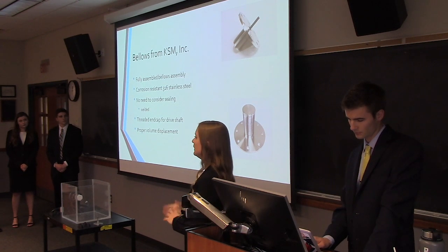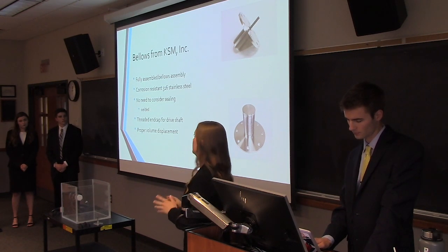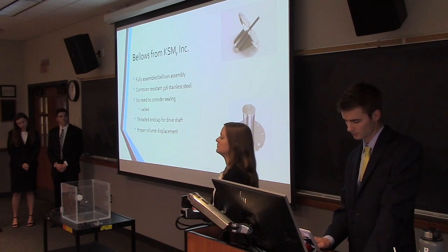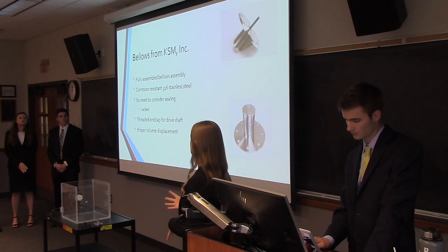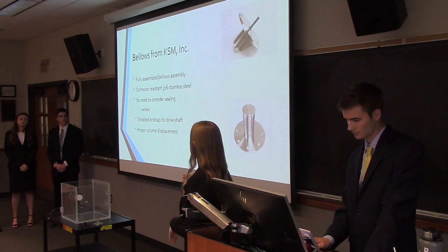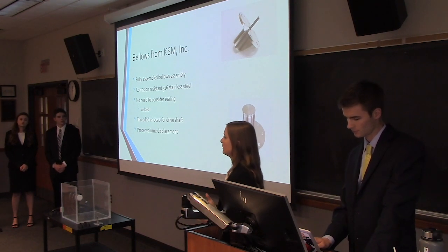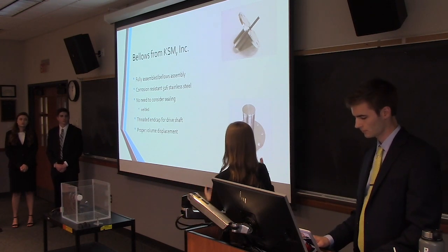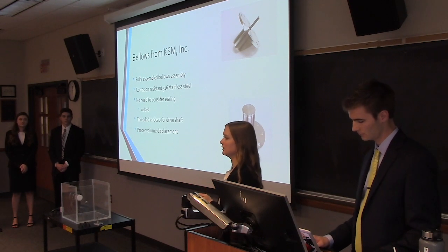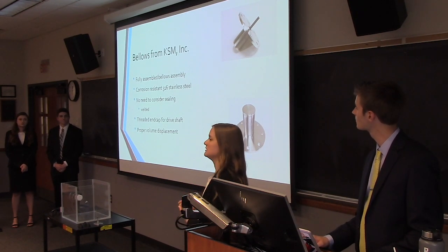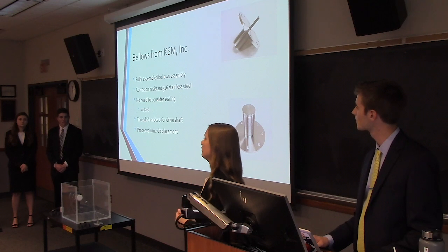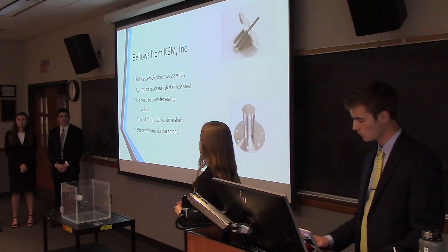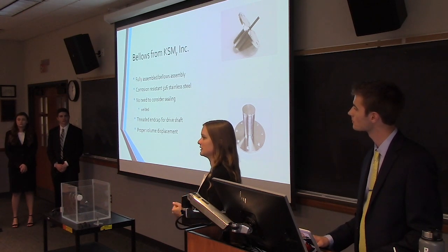There is a threaded end cap on the inside of the bellows that securely fastens the drive shaft. And the most ideal part of this assembly is the actual shape of the bellows. They are the right size and they displace the proper amount of volume that we are looking for to have a controlled amount of turbulence that we are generating.